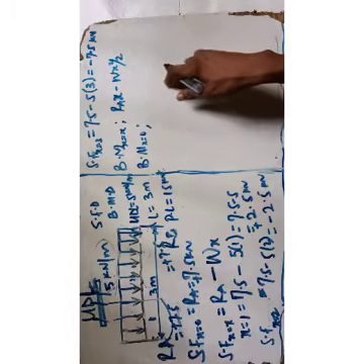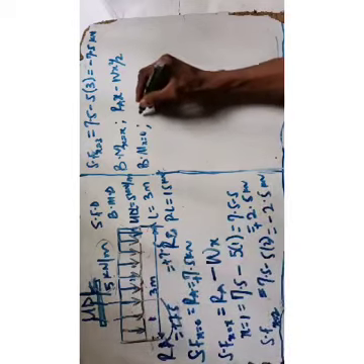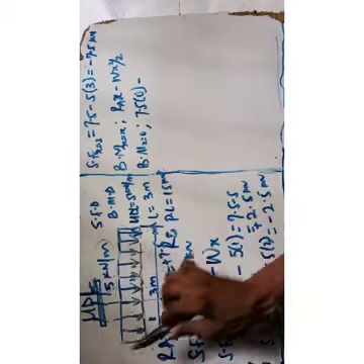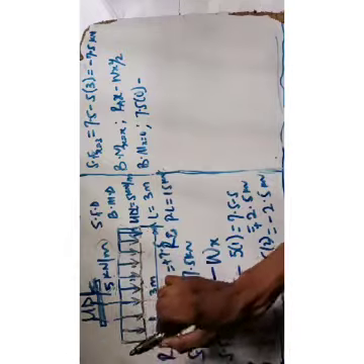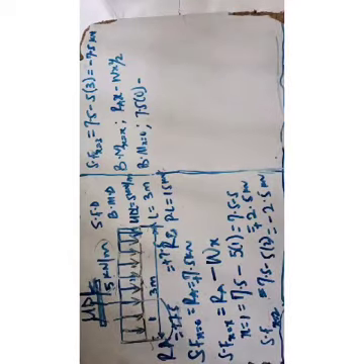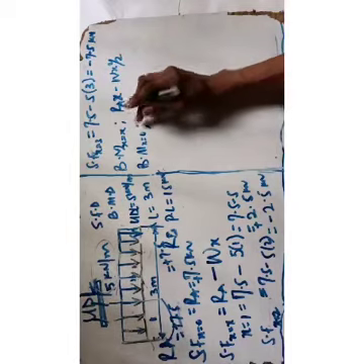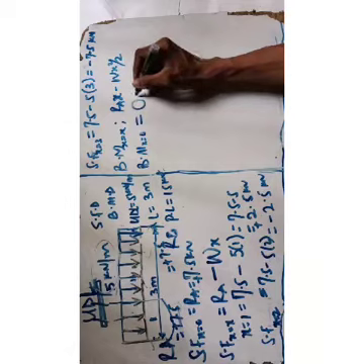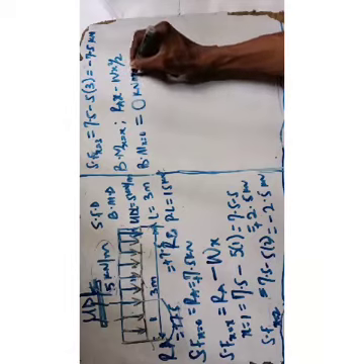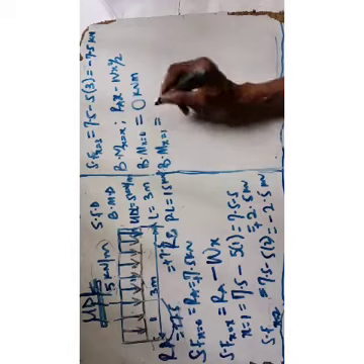So using the formula, you have it as RA, that is this, the moment you are taking is x equals to 0, that will be 7.5 times 0 minus the weight. So at this point 0, that means you are cutting, you are leaving here, that will be 5, the 5 acting here, 5 times 0. 5 times 0 at the center, and everything will just be 0, okay. So at always the beginning, I told you that your bending moment is always 0 at the beginning. So when x equal to 0, you have the answer as what? 0 kilonewton meter.